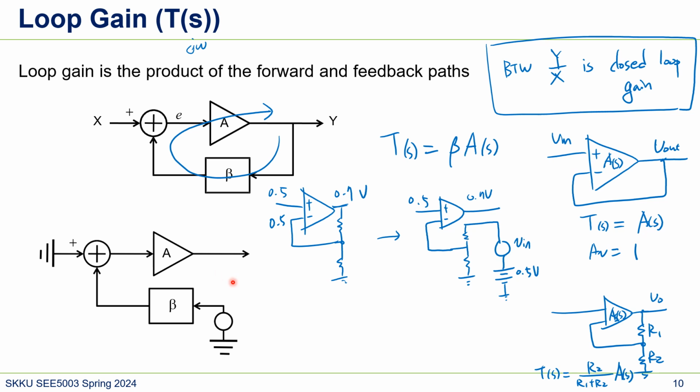So in this figure, this voltage should stay the same as the input. It's more like AC ground. So apply the VT, and then VF, and the loop gain would be VF over VT.